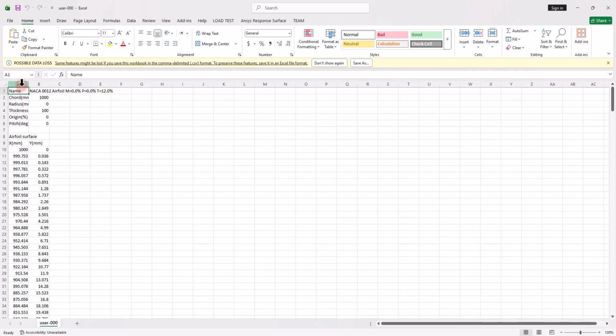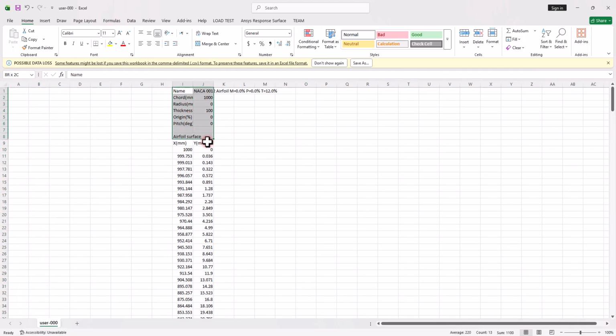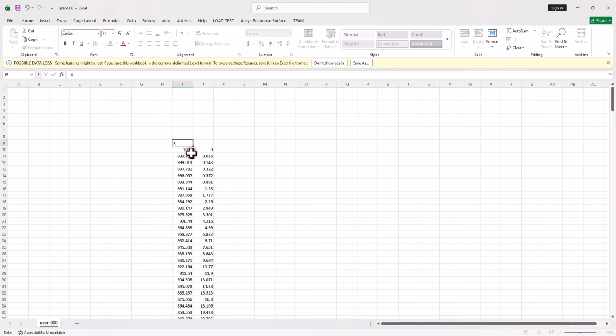So for now, I just want to cut both columns and paste them in here. These are all extra. We do not want them. All we know is that this column represents the X coordination and this one is the Y value. So from now on, what I'm doing is exactly what is expected for design modeler template. We need to define all points for the software, and we also need to group them all together because these gonna be exactly represents one sketch.